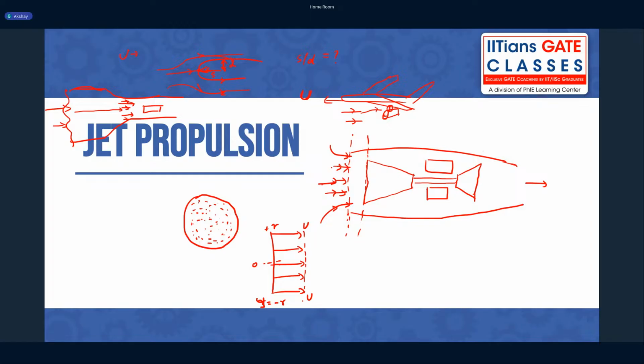But the idea here is that the flow that comes from the atmosphere might not be uniform, and that is understandable in realistic scenarios. There will be a lot of non-uniformities present. So very, very important. Why? Because our compressors, the later parts, are designed such that when the flow enters the compressor, it has to be uniform, so then only it can give me optimum performance.